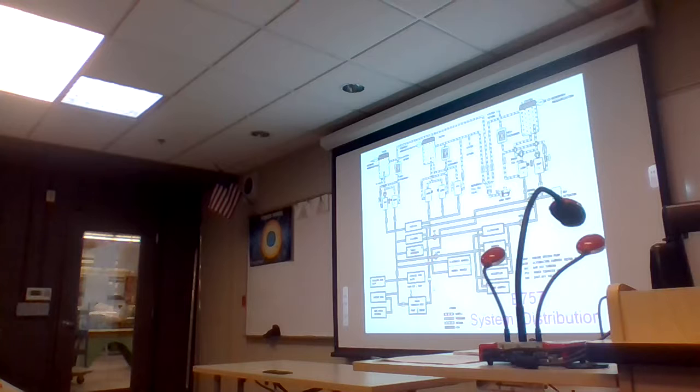Here's that power transfer unit that I was kind of looking for here. The power transfer unit is used in a lot of large aircraft in order to power a system that maybe lost hydraulic pressure from who knows what, maybe a loss of fluid. But it does it without direct transfer of hydraulic fluid. The PTU is essentially a pump and a motor in a common housing. So some of them are reversible. It'll work in either direction as a pump or a motor.